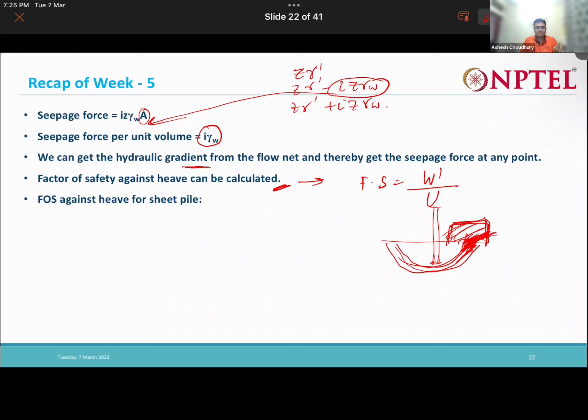Technically these things are the same, but the same thing is causing two different phenomena. One is heaving, where there is a heave of the soil. In the other case, due to the exceeding of the critical hydraulic gradient, there is flow of water through which this boiling phenomenon occurs. The point at which these two occur is actually the same: exceeding of the critical hydraulic gradient.